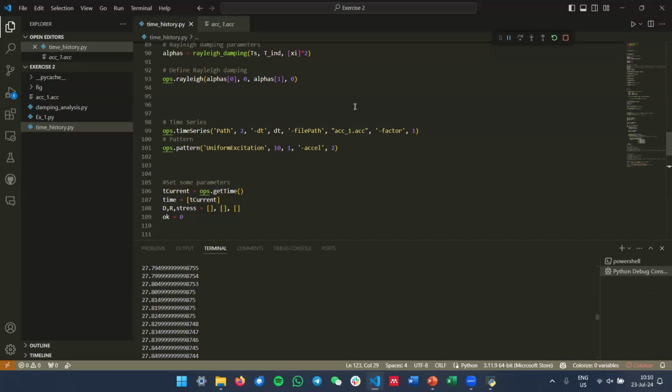You have the script that runs one ground motion for all the factors. Put that script inside another, bigger loop that changes the ground motion. Pay attention to how you store the results, and then you are done and everything is clear. Now everything is ready for running the IDA.